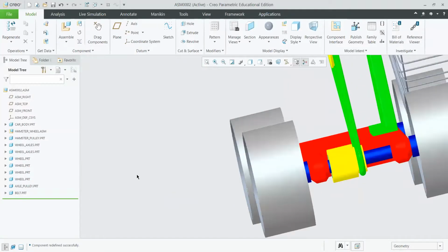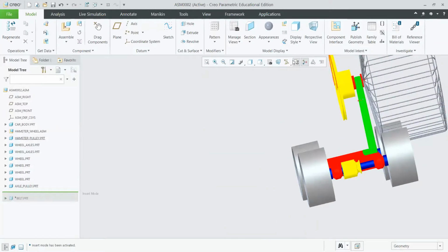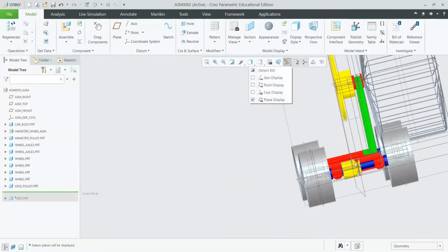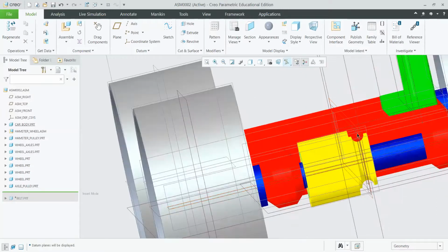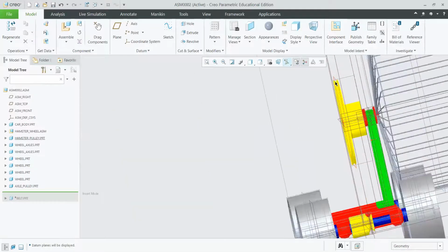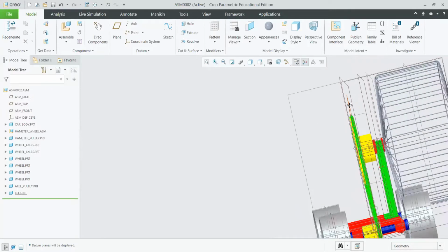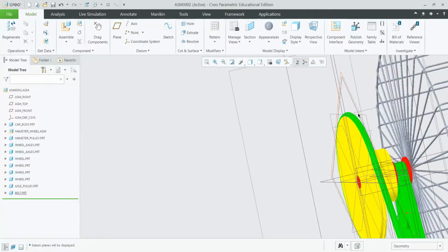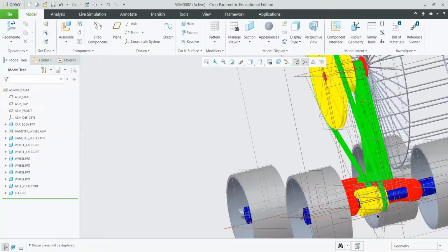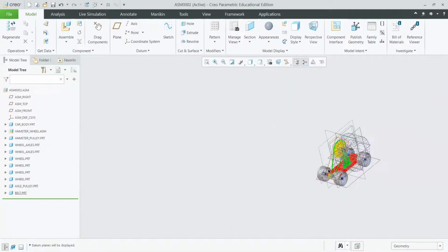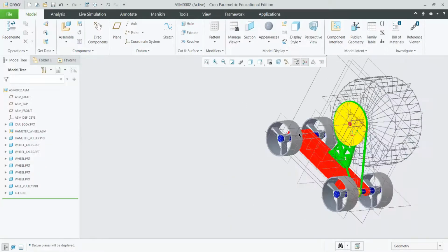So when I put this pulley in here, the plane that goes through the middle of this pulley actually lines up with the middle of this pulley. I made that constraint. So if you align the belt to this plane up here, then it's automatically going to be aligned to the plane down there. So you don't have to do both.